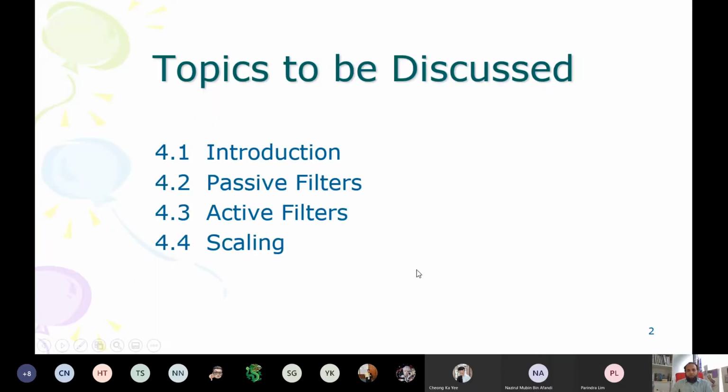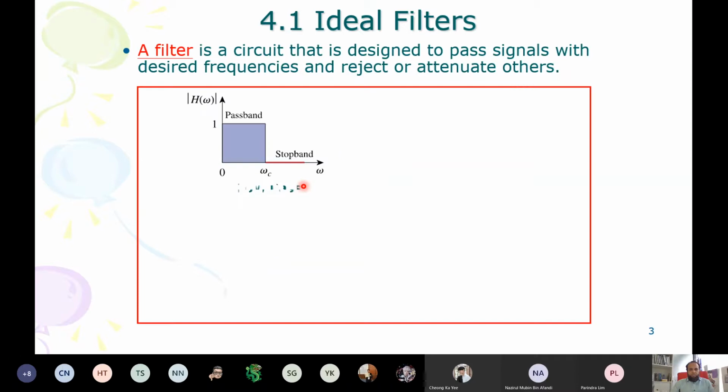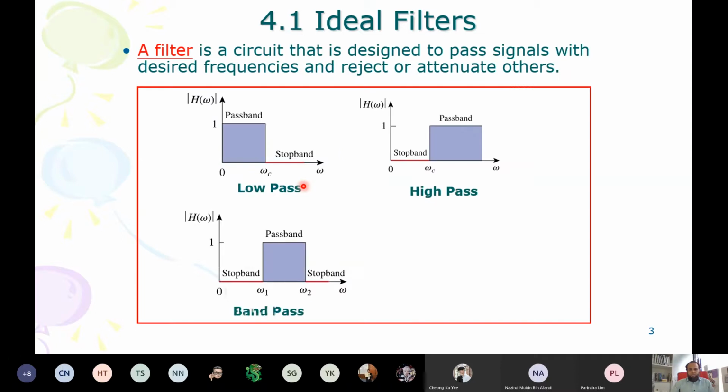All right. So basically, we are talking about filters, active filters and passive filters. The passive filters are the ones without any active component. Active component means that they have some sort of a source, or something that can add energy or power to the circuit. So just R, L, and C. And active filters are with op amps or transistors, right? So these are the ideal filters.